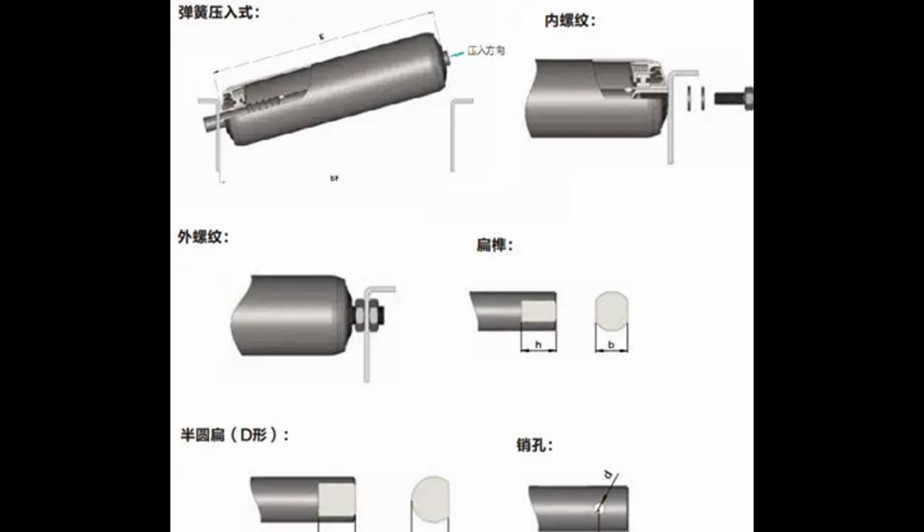1. Spring press-in. A. The most commonly used installation method in non-powered rollers; installation and disassembly are very convenient and fast. B. There needs to be a certain installation margin between the inner width of the frame and the roller, which will vary according to the diameter, hole diameter and height, usually leaving a gap of 0.5 to 1 mm on one side. C. Tie rods need to be added between the racks to stabilize and reinforce the frame. D. It is not recommended to install sprocket rollers with loose connections such as spring press-in.